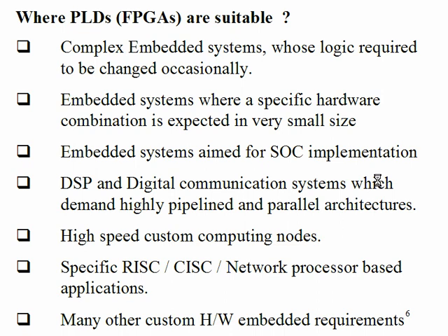So FPGAs are carrying both the advantages. FPGAs have parallel concurrent working hardware, so they are on par with the ASICs. Simultaneously FPGAs are reconfigurable, so they have the advantages of microprocessor or conventional microcontroller based development. You have seen now, FPGAs are competing with ASICs because the way in which ASICs can do jobs in parallel hardware, FPGAs also can do. FPGAs got the advantage of microprocessor, microcontroller based development because they are reconfigurable. Got the point?